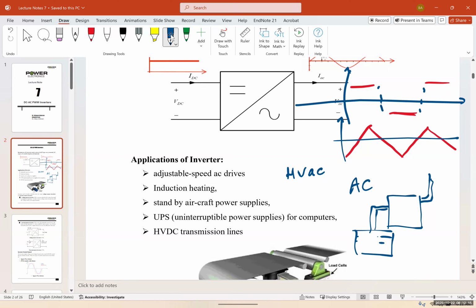That's the reason you see the outside unit has radiators, for cooling the gas as it is compressed and becomes a liquid. It's pumped to the inside unit, and then the pressure is released. It absorbs the heat to evaporate the liquid, becomes a gas, and then goes back to the compressor.